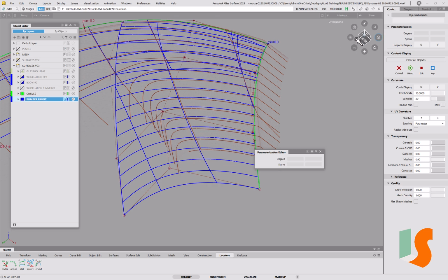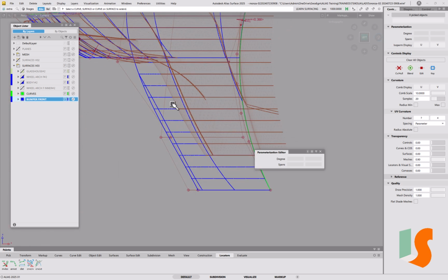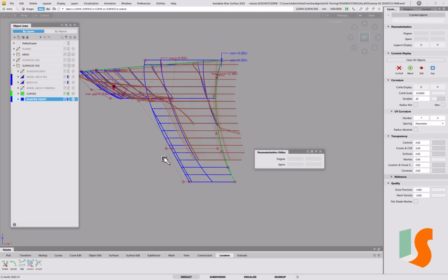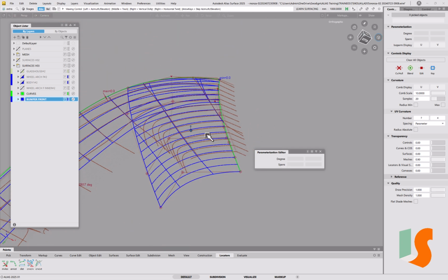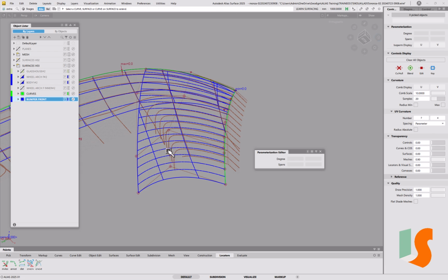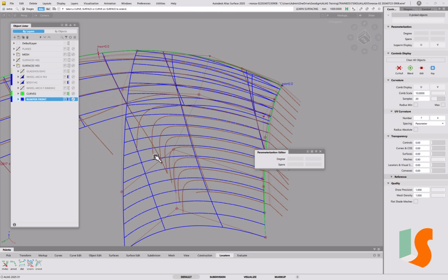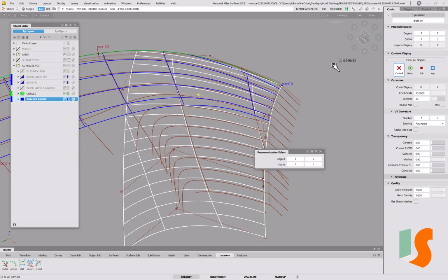And let's have a look at that in the side view, just see what those CVs look like. So they're crossing over. That doesn't mean it's wrong, it just means that we've had to extend this way beyond, and it's going to curve up. The only thing I can see is that, though it might be crossing over, these points look a bit not quite right, that it's sort of zigzagging here. So maybe that point could go further in the X and then bring that one back, push it back towards the back of the car, so that that's more all going one way.